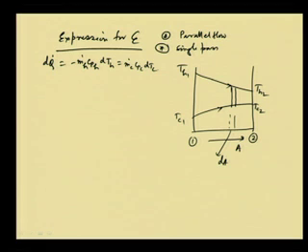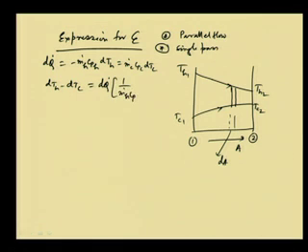TC2 is higher than TC1, therefore dTc is a positive quantity, so we have not taken any negative sign. So, from here we can write that dTh minus dTc is equal to dq dot, which is common, into minus 1 by m dot h Cph plus 1 by m dot c Cpc.